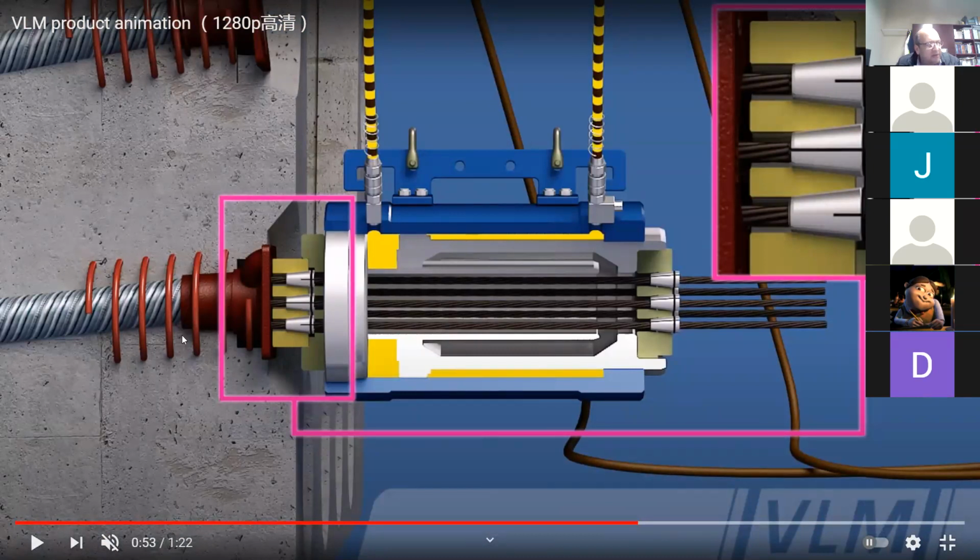This part here is gonna be helping you to control the amount of force that you put in here. And this is not gonna be it. This just comes with the anchor, with this Fressinet connector. It comes with it. But also you can see lots of reinforcing in this location, like ties and things like this. Otherwise, you can just break the end of the concrete from this pre-stress business. Interesting. Good question. Thank you.